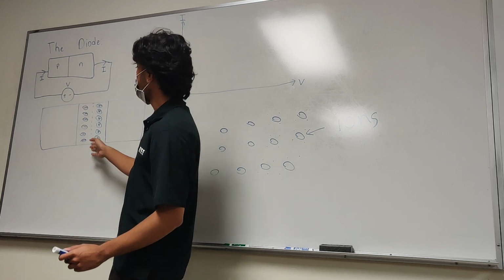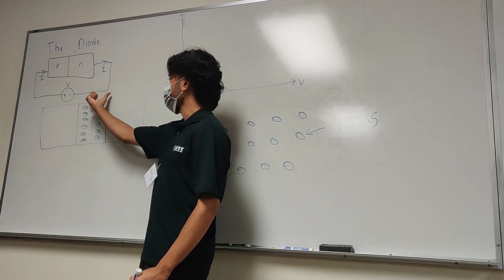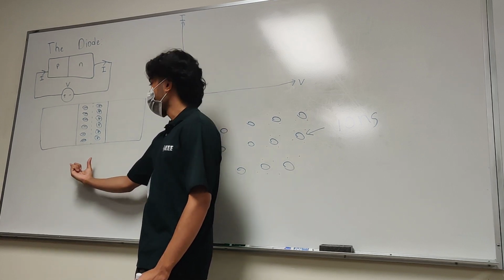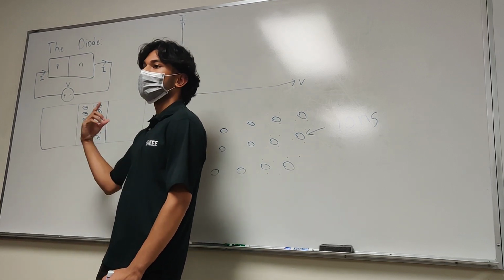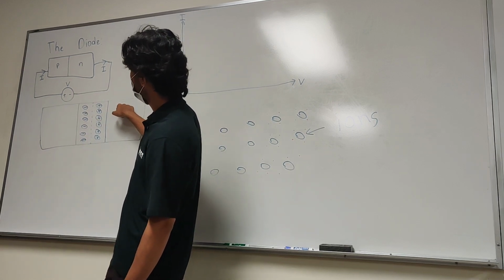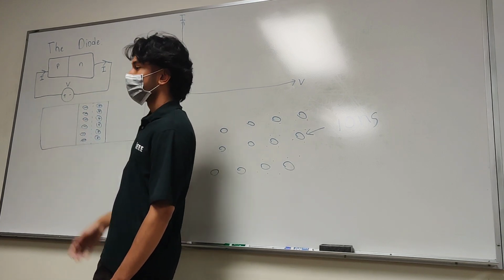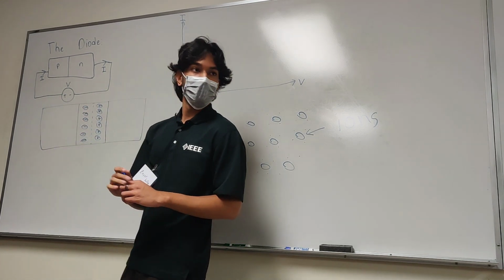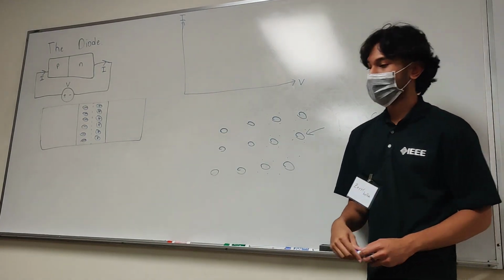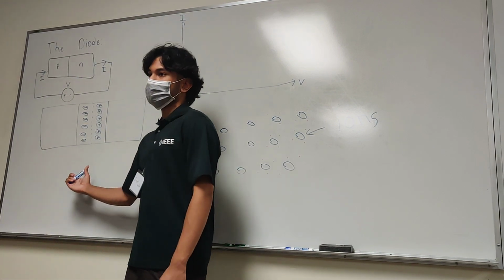And what these ions do is they set up an electric field, which in turn creates a voltage across this region, and we refer to this region as the depletion region. The reason for this is we no longer have free charge that can move around. Any, let's say, electrons that are over here that drift into this region get pushed across. Okay? Does that make sense so far? Can all of you see that? Somewhat? Yeah? Okay, cool. So this sets up our depletion region.